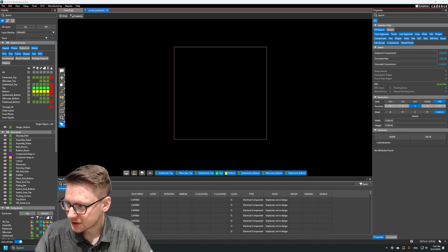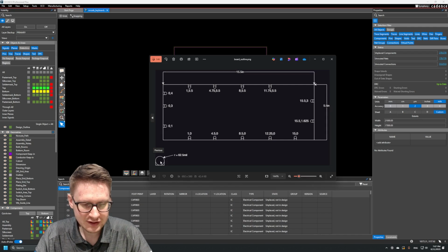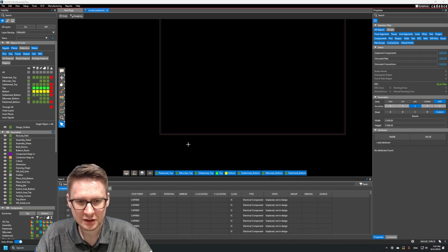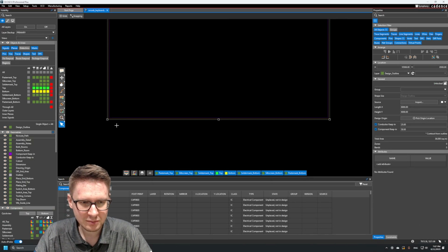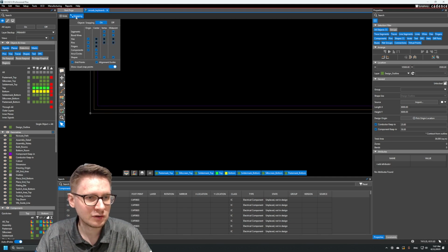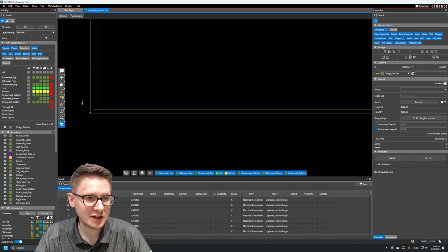So in this drawing, each of these divots have a little hole which has a radius of 62.5 mils. What we need to do is set up a grid that will allow us to easily draw this using the built-in functionality. So first thing I want to do is, if I select this board outline, make sure that my origin starts in this bottom left corner. So I can click on pick origin location, and you'll notice that I already have a snap indicator. If you're not seeing it, just click the snapping at the top, make sure that it's on, and click in this left corner.